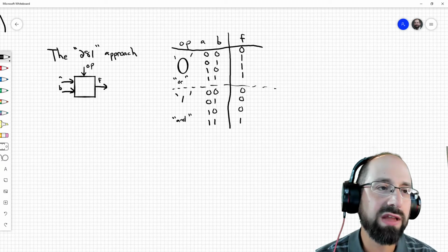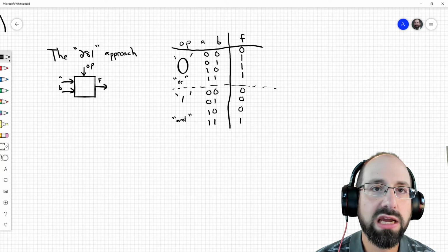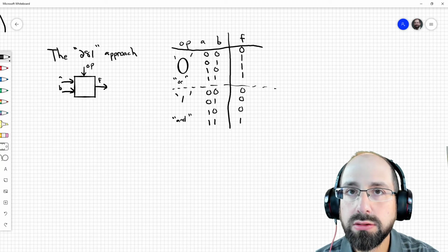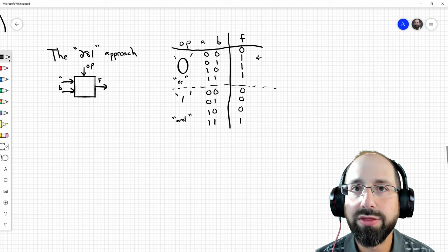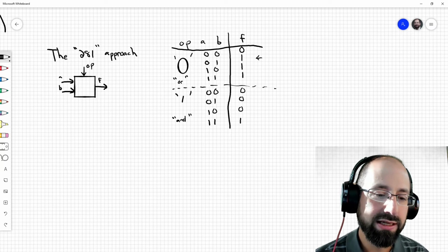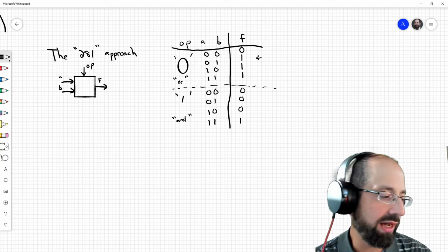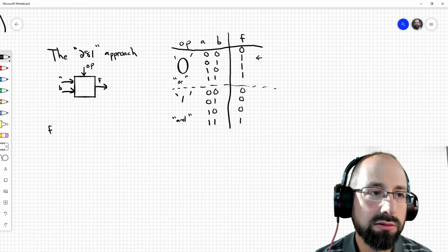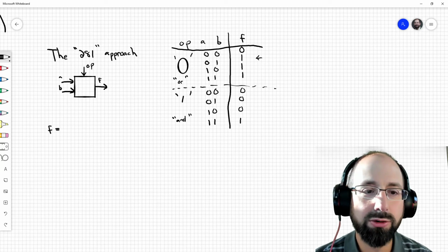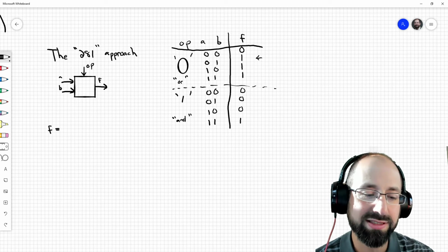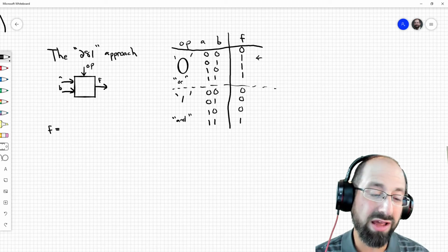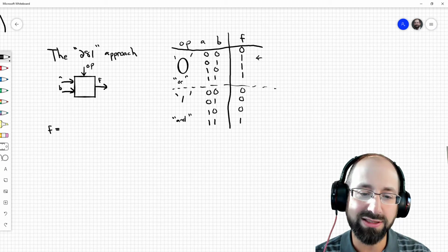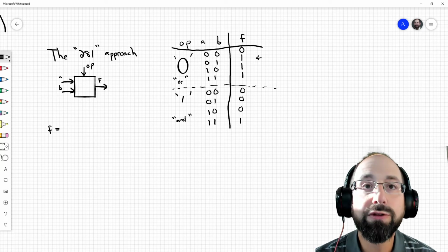How do I minimize this truth table? Well, you can start certainly with the sum of products representation, which is for every input combination that results in a 1 in my output, treat that as a separate term in my sum of products representation. If this only sounds slightly familiar, well, blame your 281 instructor, or remember that we're just showing this as an example to compare to sum of products, right? We have a bunch of ANDed terms together, and we have a bunch of ORs of those, and it's a 2-level circuit corresponding to whatever function we're interested in.